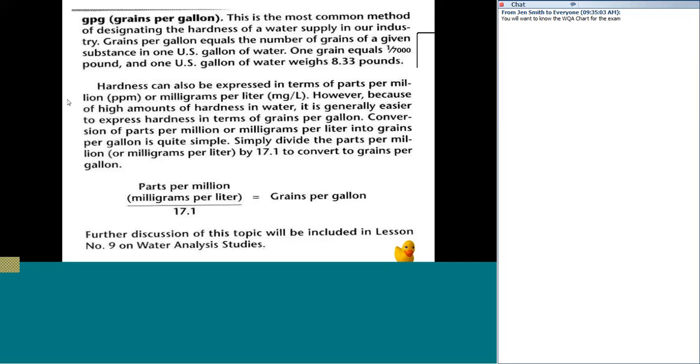That's pretty big. That's huge. It's not uncommon to have 20 grains per gallon of hardness in the water and 4 people in the house. So you get a softener that's taking out close to 7,000 or 8,000 grains a day. That's not uncommon at all.